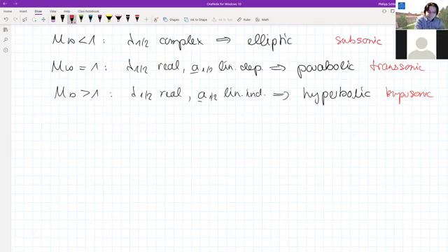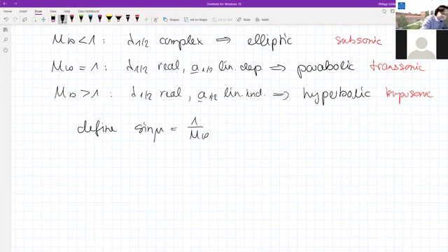And of course, in the middle, you can say it's kind of a transonic regime. But now the nice thing is we can go even further with the physical interpretation of all of this. We can really try to understand from a physical point of view how this change of mathematical properties actually happens. Now, in the language of Prandtl and Glauert, we can define an angle, mu in this case, which would be 1 over the Mach number.